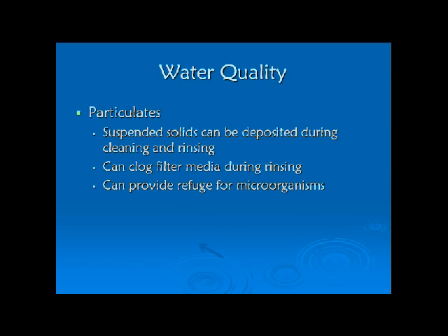They also have kind of an interesting effect, and so if you have water that's, we'll say, contaminated with some bacteria, there's some pretty effective ultraviolet systems that you can put in line. Basically, usually right where it comes into the building, you plumb this in, and it shines a very intense ultraviolet light through the water as it passes through the pipe.